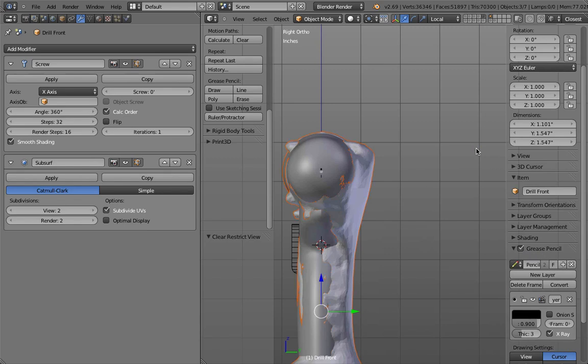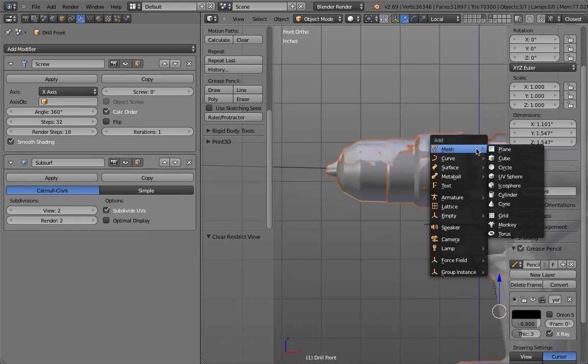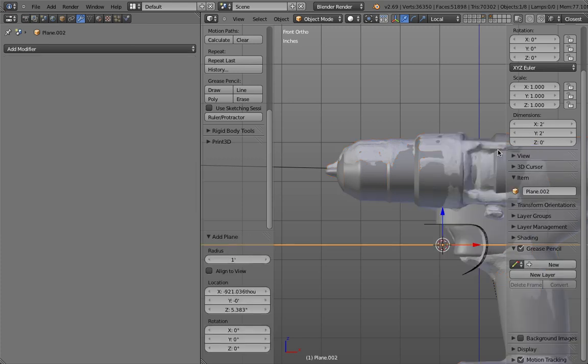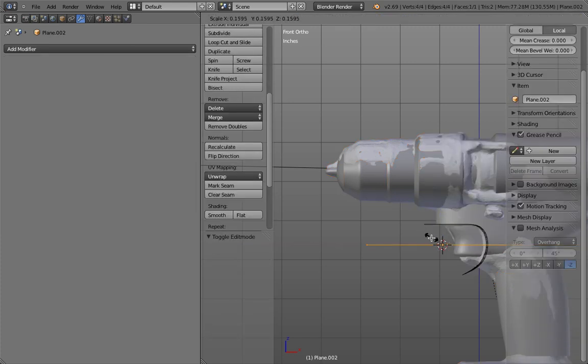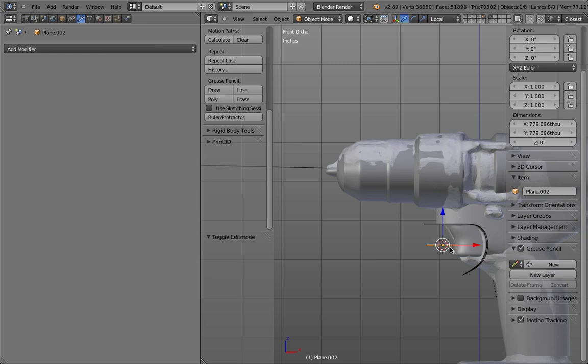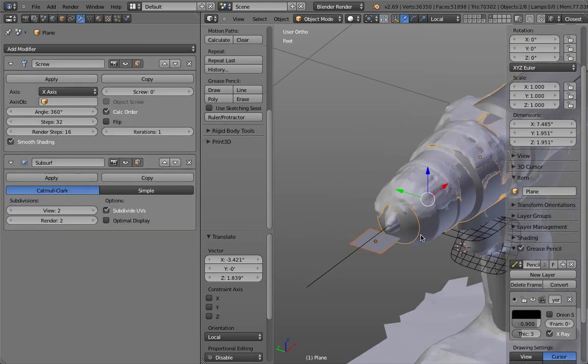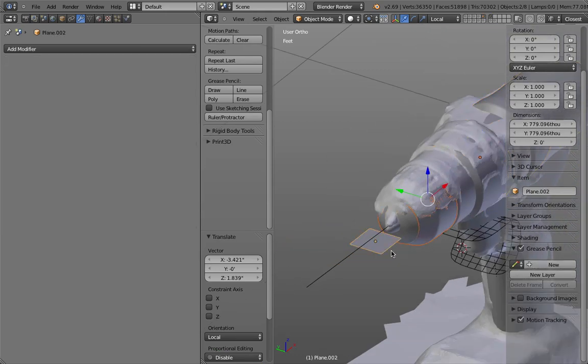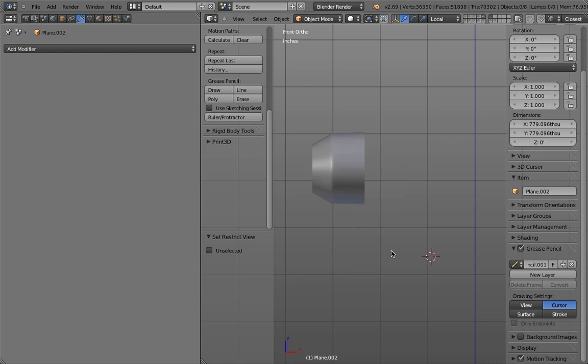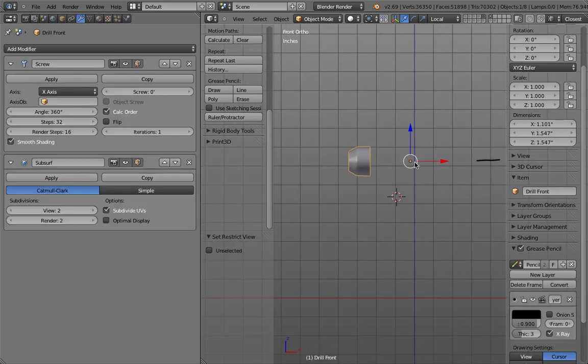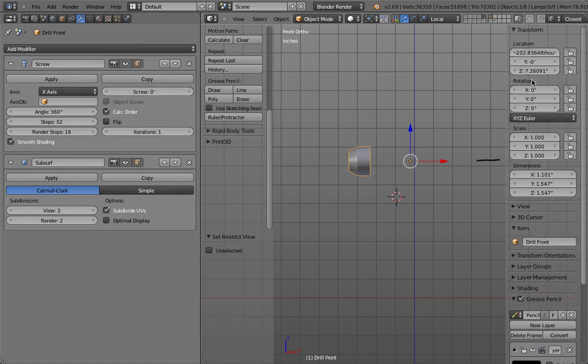So let's see, the 3D cursor is still positioned at the same position, so I again start, for example, with a cube, scale it down, move this cube, and now this is a really important step to remember. So this object has, where's this one positioned? Z, kind of like there.